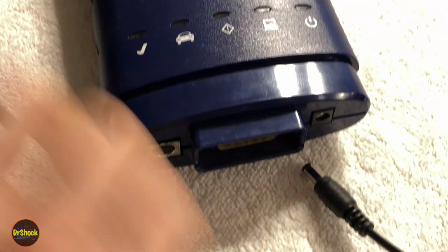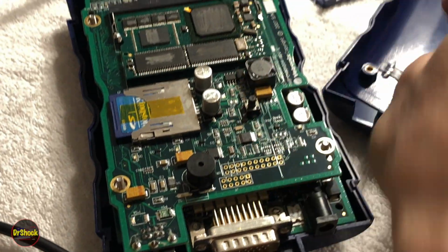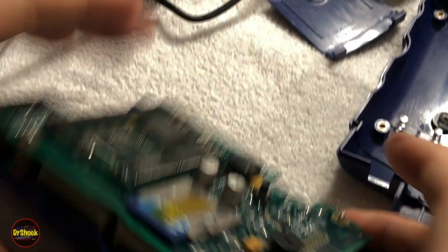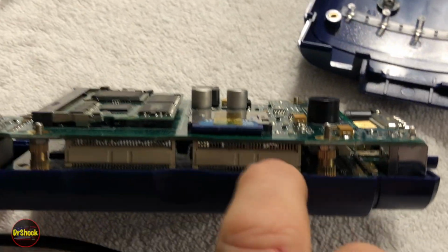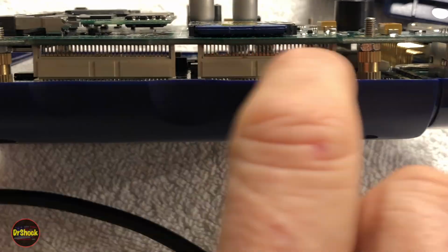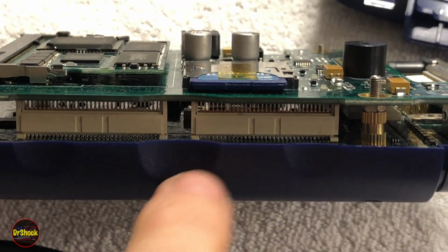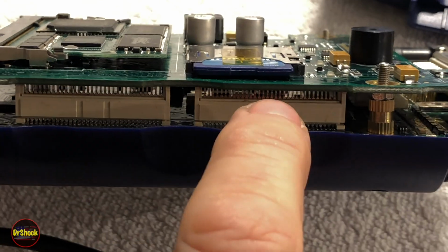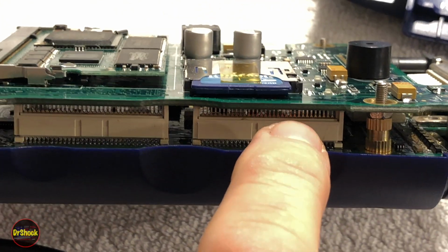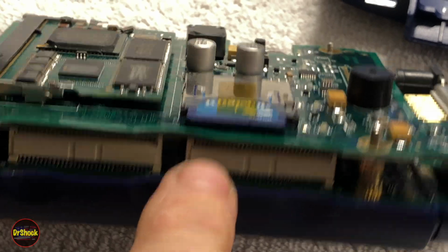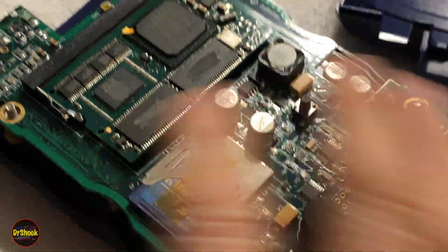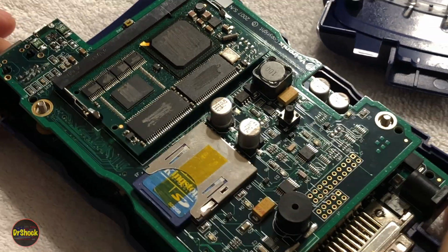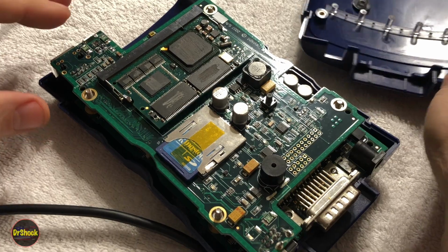So what we found on this one, after we reflowed that board that I showed you earlier, as we were putting it back together, what we saw is we had some oxidation on these two connectors that connect these two pieces, these two boards. This is a two-board setup like we showed earlier. So I hit this with some DeoxIT G5, let that set up and then blow it out, and then we put it back together and we reinstalled this board, and that seems to have done the trick. So this one's ready to go back in service.